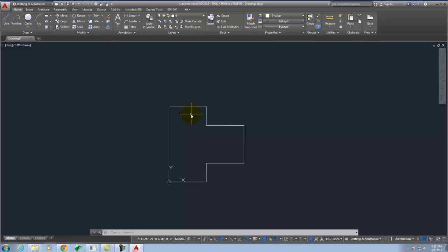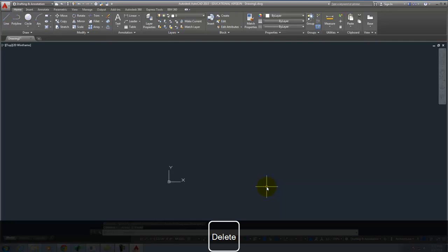Okay? AutoCAD has improved a bit, and I wanted to explain to you how these coordinate systems work before we got into dynamic input. So when dynamic input is on, however, it's going to take your command line and give you a few key text input boxes right by your cursor. So I'm going to go ahead and turn that dynamic input back on. It's blue now. I'll just delete this for right now, and we'll draw again. I'll start again at point 0, 0.